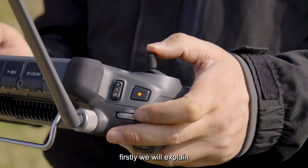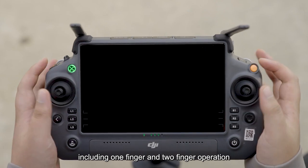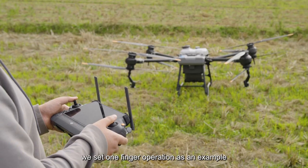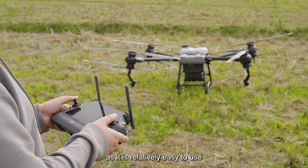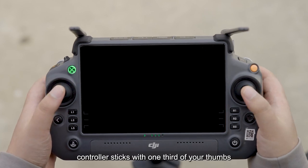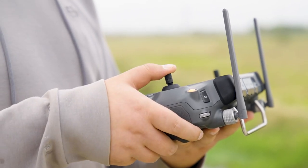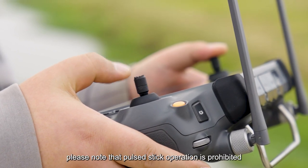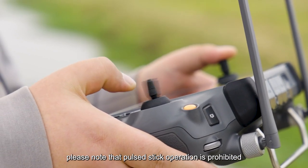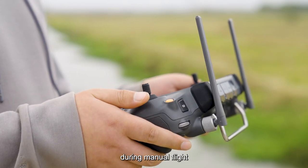Firstly, we will explain how to use the remote controller sticks, including one-finger and two-finger operation. We set one-finger operation as an example as it is relatively easy to use. Press the remote controller sticks with 1/3 of your thumbs and hold the remote controller with other fingers. When operating the remote controller, please note that pulsed stick operation is prohibited, and fingers are not allowed to leave the sticks during manual flight.